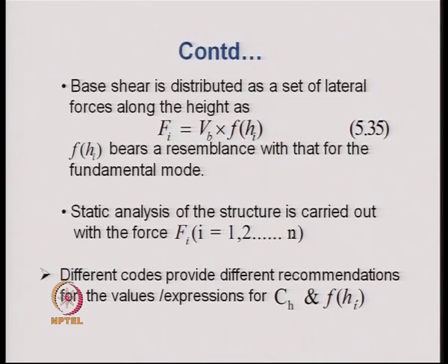Most of the time, in both the seismic coefficient method and the response spectrum method of analysis, the load that is obtained in each mode of vibration in the case of the response spectrum method, and the load Fi that we obtain in the seismic coefficient method, is divided by a factor R, which is called a reduction factor. This reduction factor reduces the total load coming onto the structure due to earthquake.